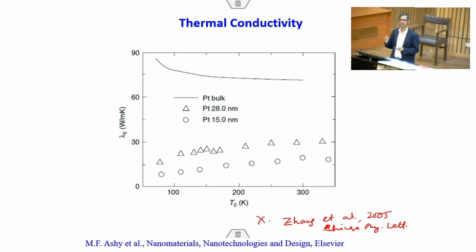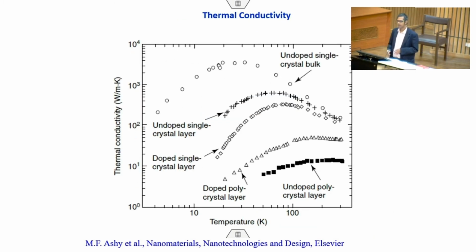Very simple. You have a particle in the air, the light can get scattered easily, right? Same thing happens when you have a large number of grain boundaries in a material. The electrons, while moving inside the grain material, will come into contact with the grain boundary and get scattered and move in other directions. So while taking the heat in the right direction, they will be bringing the heat back, right? That's why the thermal conductivity decreases. This is the first thing for the 2D single layer materials. Observe. Now what about multi-layer materials?